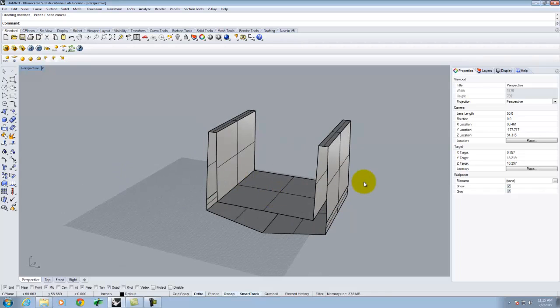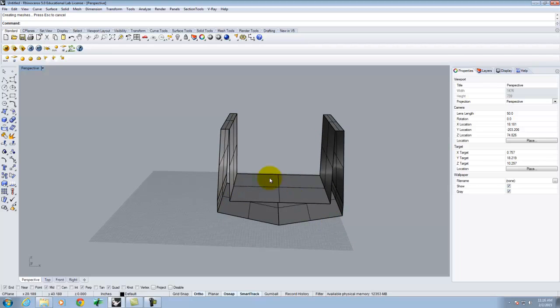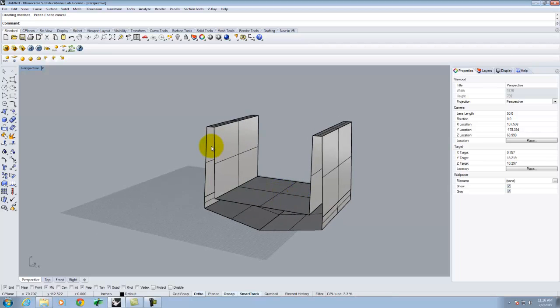Now when I get to the end, I'm going to want to build a surface on each of the ends, and I can take all of my curves, join them together, and patch the end. The challenge with patching is when we go to do the chamfers of the surface, it's going to have an issue right here because of the way the surface comes together. So it's actually a little bit better to do this as separate little surfaces.